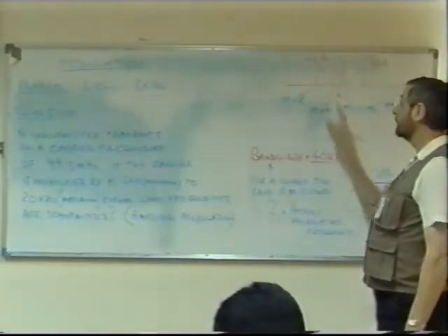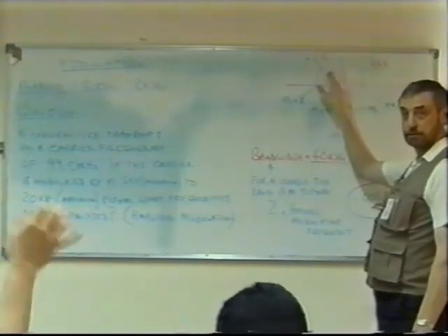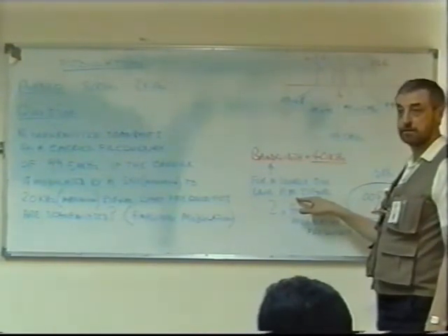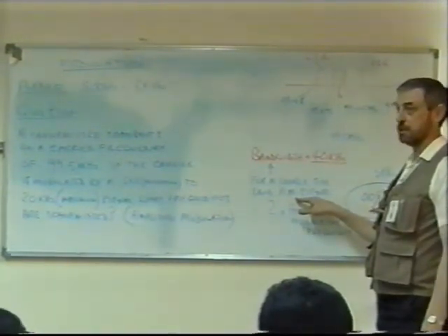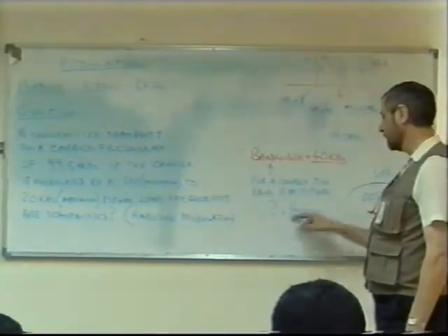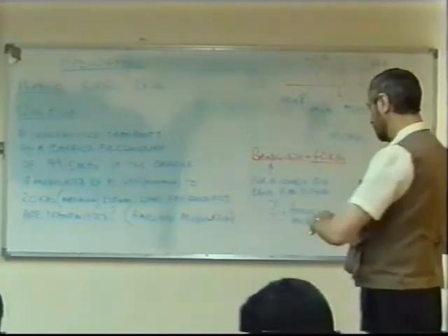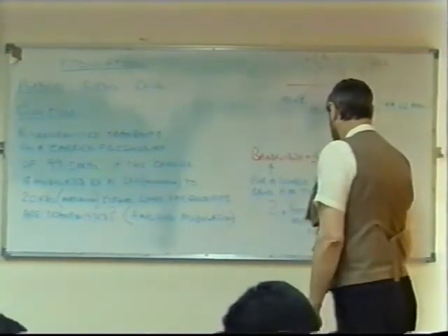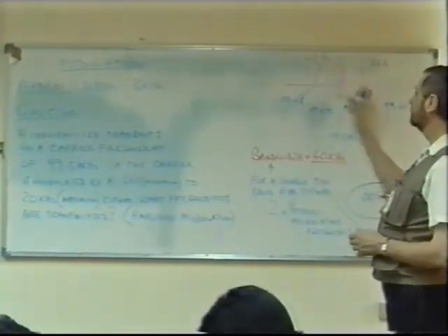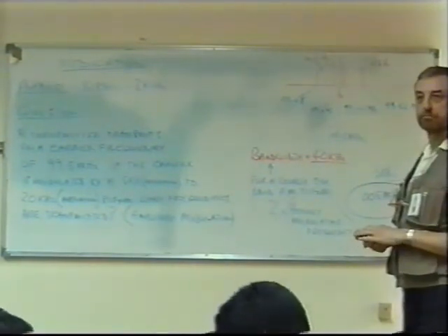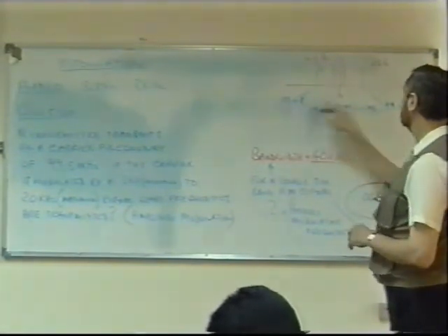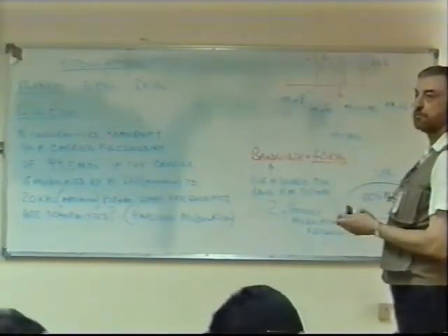For a double sideband, this is where we're using an upper and a lower sideband. Double sideband, AM signal. What does AM stand for here? Amplitude modulation, yes. For an AM signal, the bandwidth is equal to 2 times the highest modulating frequency. So you've got to find out what the highest frequency is used for modulating. Twice that is the bandwidth of your transmission. So you take 99.52 and 99.48, you can take that away from that and you should get the same answer exactly.